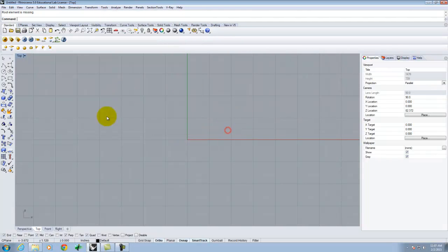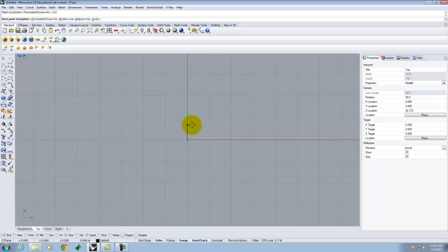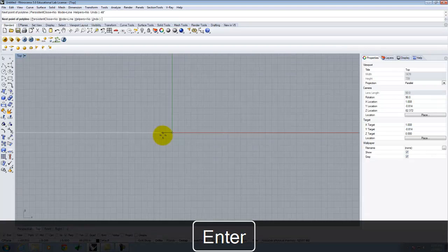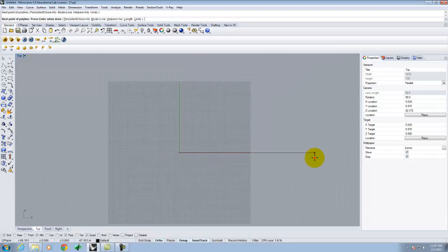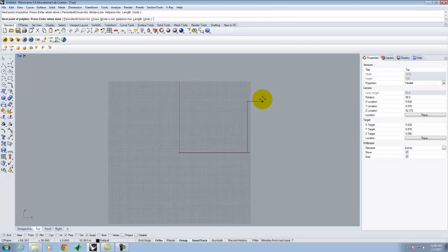It should be on. I'm going to start with the Polyline tool right here, and I'm going to start at point 0,0 as I draw. On this little drawing, I put point 0,0 right at the inside corner as a place to start. Then I'll start my drawing. I'll go over 48 inches in that direction. Then we zoom out a little bit. Then I'm going to go up 36 inches. So again, I'm doing length and then the direction that I want to go.